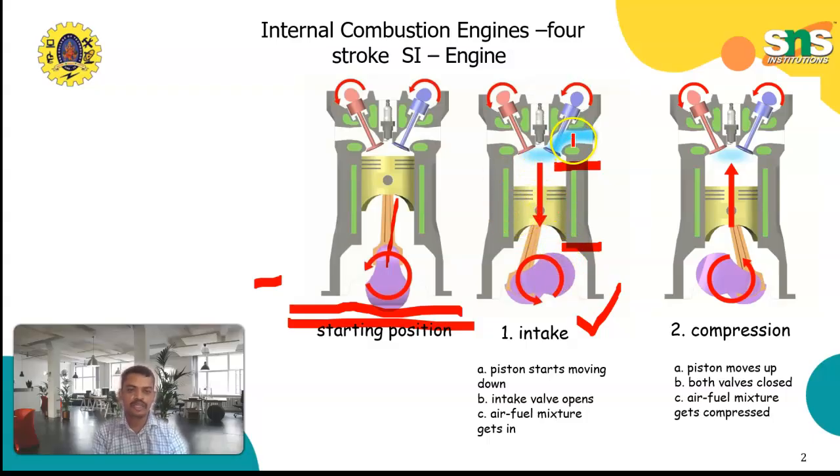During the suction stroke, the inlet valve is open. The air fuel mixture enters into the cylinder. When the piston reaches the BDC, the suction stroke is completed, and it starts the second stroke. Slowly the inlet valve goes to the closed condition.